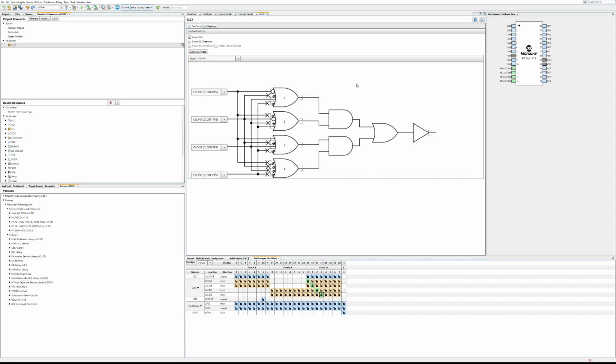So this is a standard AND OR gate chain, but there are a variety of different modes you can put the SR latch into. So you can, for instance, use an SR latch, which gives you your set, reset, latching behavior. And you can use any of these 8 inputs here, going through an OR gate into the set pin, or any of these 8 inputs here, going through OR gates into the reset pin. And you can invert signals as desired.